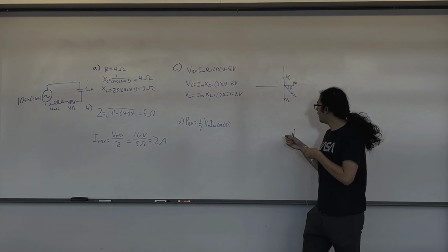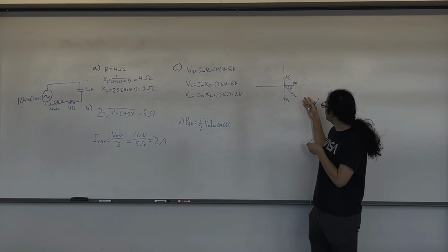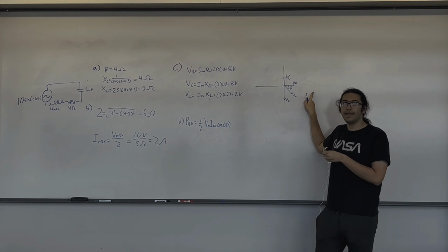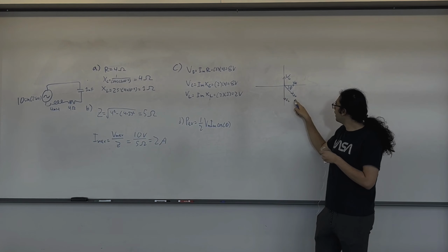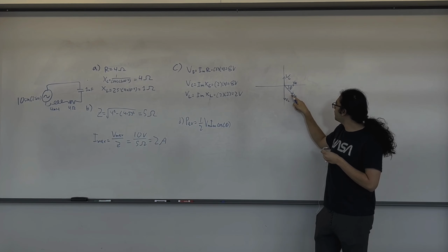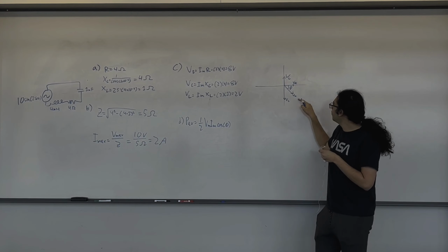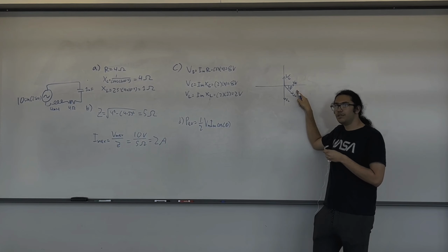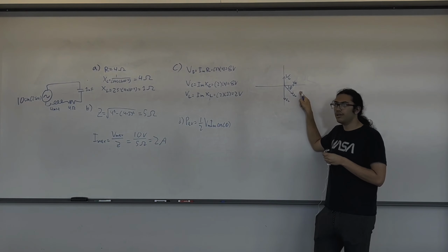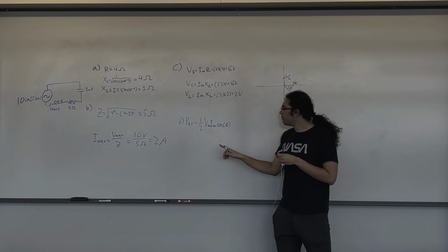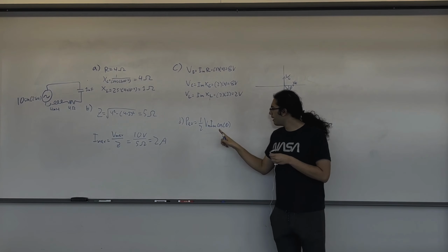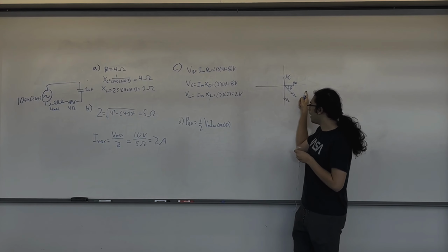And we can actually graph that on our phasor chart here, and we can see that we have our VL pointing up, our VC pointing down, and our VR pointing to the right. And then with this, we can also plot our max voltage on this phasor chart. And we'll notice that this max voltage is actually going to be going below the horizontal with a certain angle phi. And this angle phi is really important because this helps us calculate our average power. So our average power is going to be equal to 1/2 times our max voltage times our max current times the cosine of this angle phi.